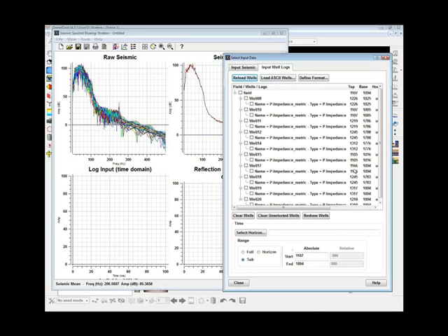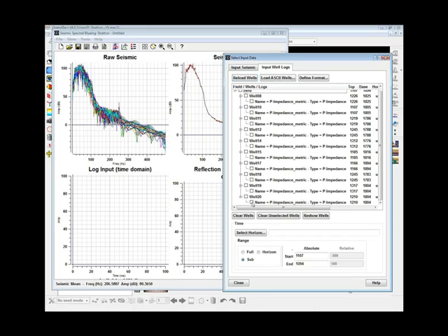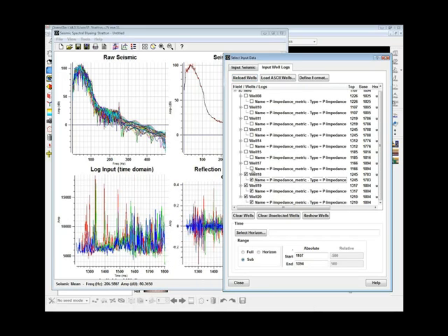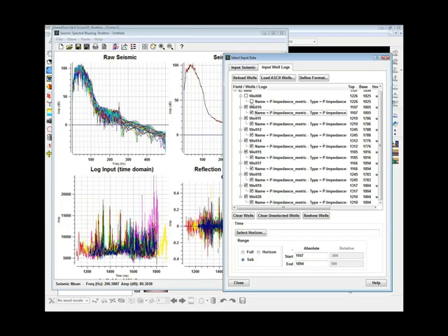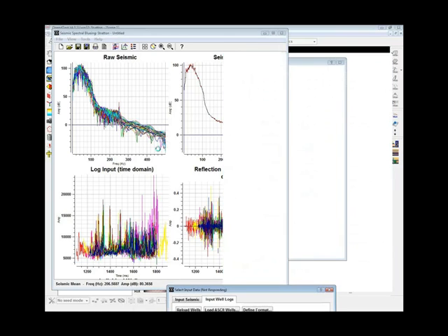First of all, in this window, this will load the wells loaded in OpendTect with a list of logs that are suitable for this process. That is either an impedance log or any set of sonic and density logs. So I could create on the fly impedance logs by selecting sonic and density. As I'm selecting the wells here, you can see that the charts are displayed at the same moment, and that I'll be able to go on by selecting the data.